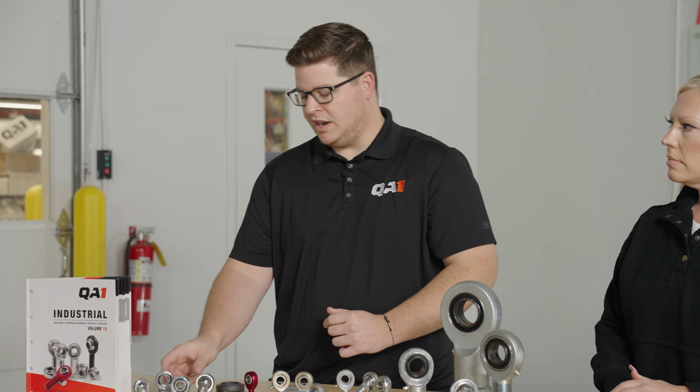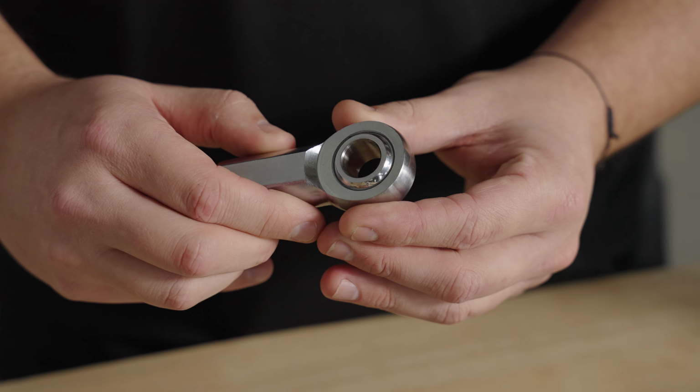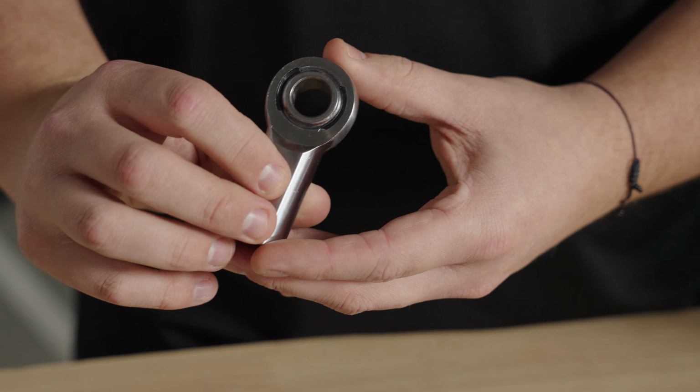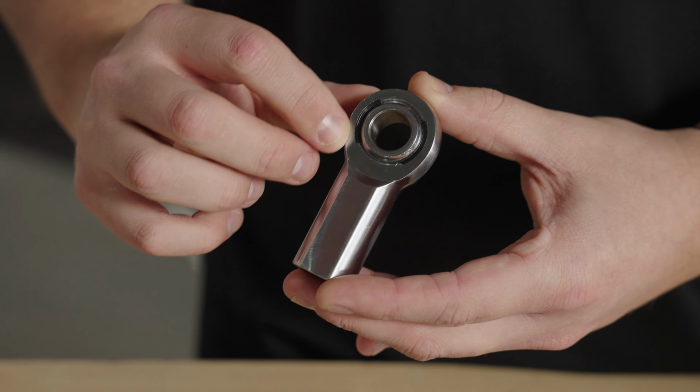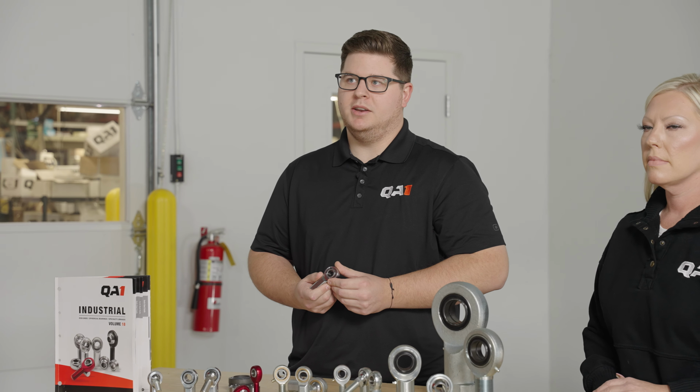Lastly, we'll talk about loader slot rod ends. These rod ends are constructed by inserting the spherical ball through a precision loader slot in the housing, which is followed by injecting a self-lubricating material. The unique combination design results in a best of both worlds: metal-to-metal support for heavy shock loads and very smooth operation for low loads, delivering improved load distribution and high wear resistance.